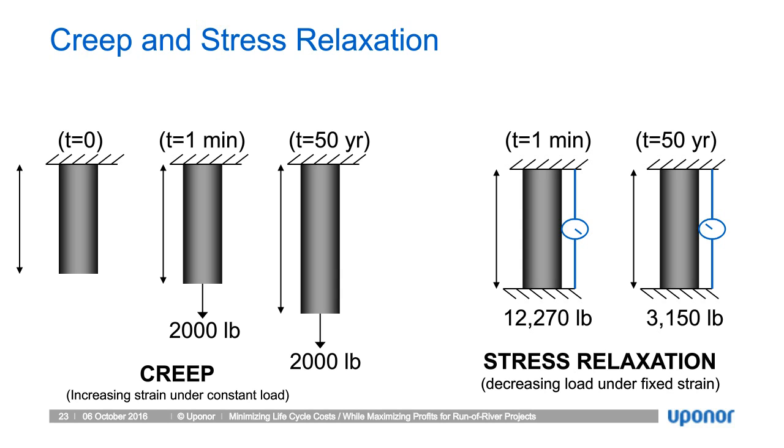What this is presenting on the right-hand side is that if we apply a stress to the pipe, this is 12,000 pounds, over time the internal stresses within the material will reduce. So it will compensate for that.